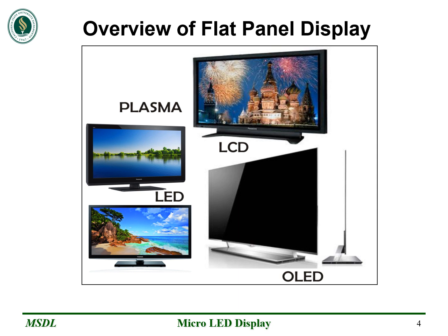The flat panel display is divided into two types of display, emissive display and non-emissive display. In emissive display, the image is produced directly on the screen. Phosphor converts electron beam or UV light into visible light. Example, plasma, CRT, LED and OLED. In non-emissive display, light is produced behind the screen and the image is formed by filtering this light. Example, LCD display.